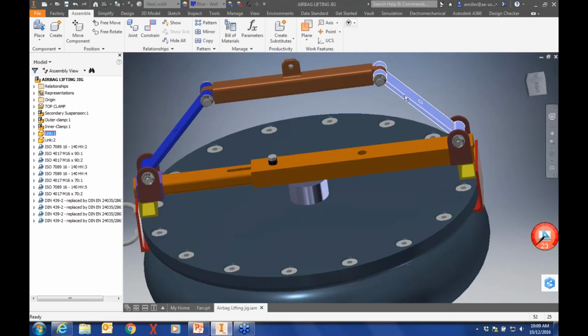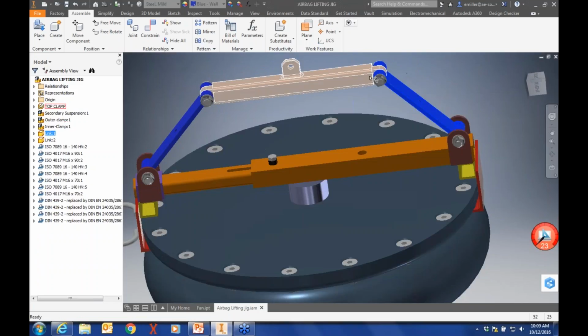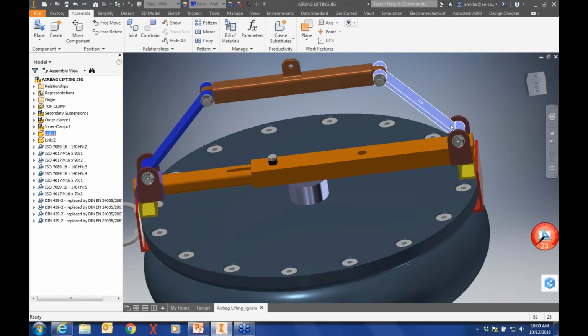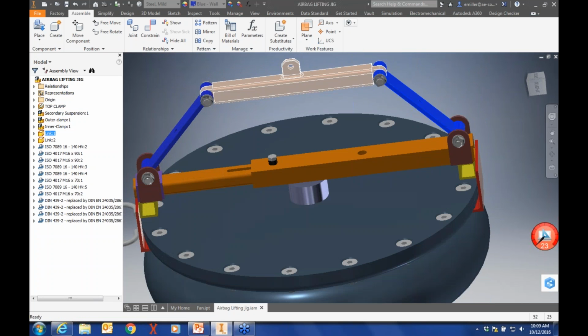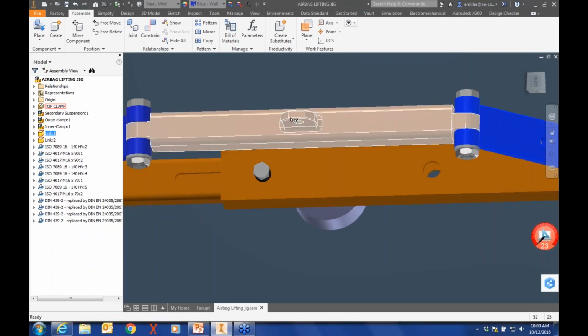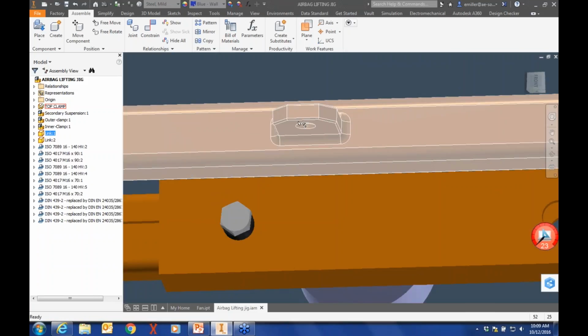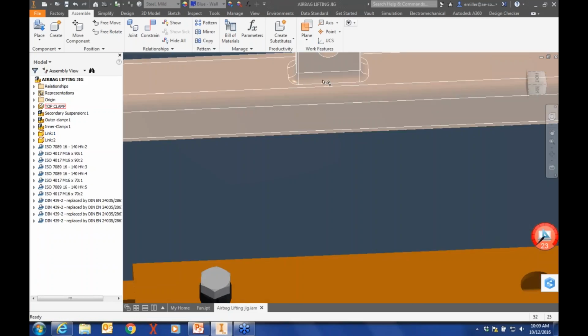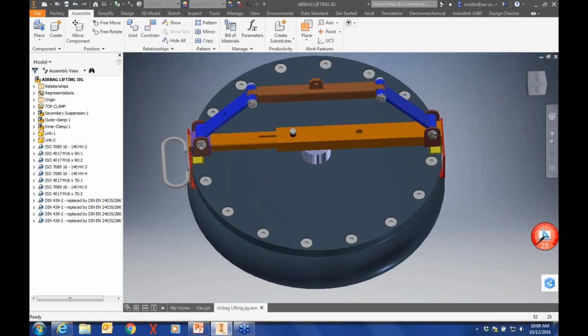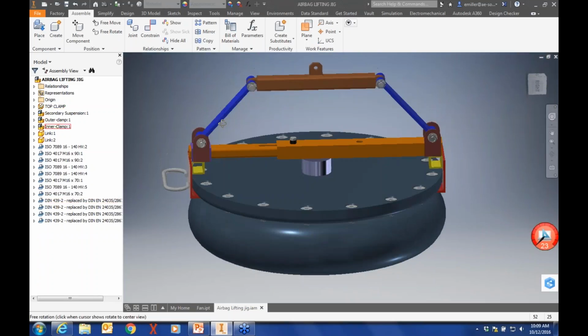Is this channel too narrow potentially? If you think about how that's going to put a force around the bolts, or even up on top, do we need to make this piece a little bit thicker to make sure it has enough strength? Are the welds there placed properly, and is there enough there?